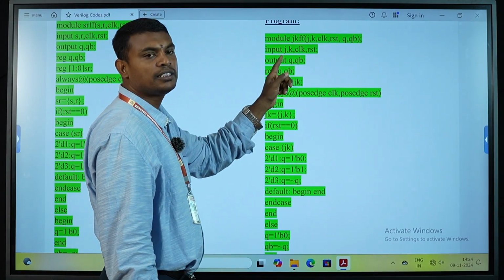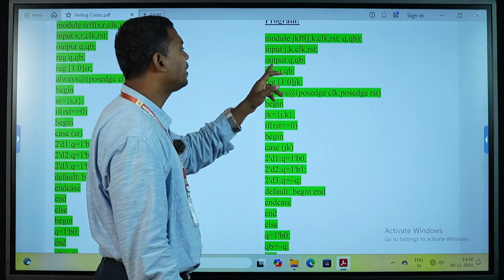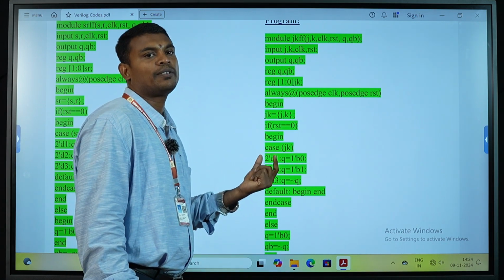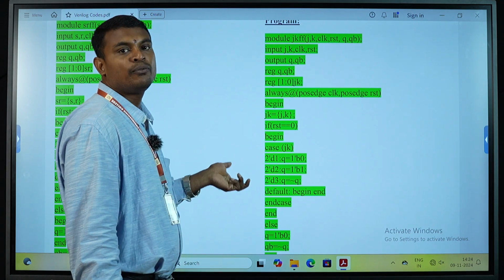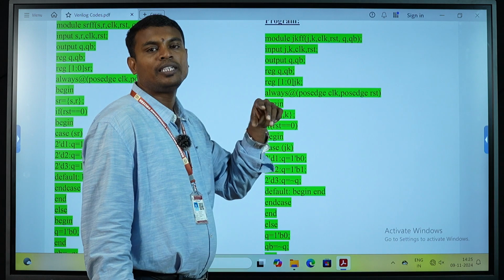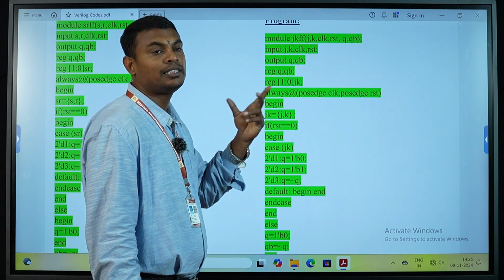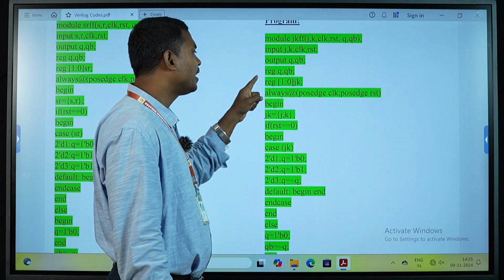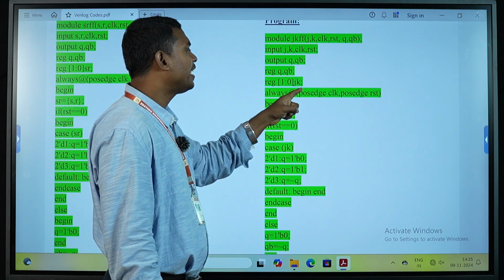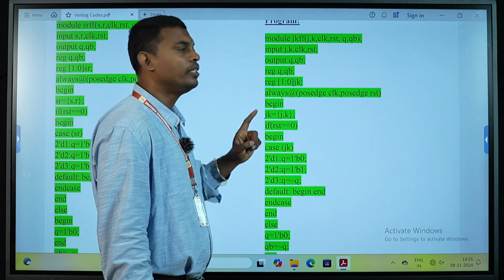Inputs are J, K, clock and reset, outputs are Q and Q bar. You know that we need to store the output in a register. Why? Because these outputs are to be fed along with my current input, so that my output will change its status. That's the reason I am making a register to store my output values, and I am also declaring the JK inputs to be of 1:0 length.